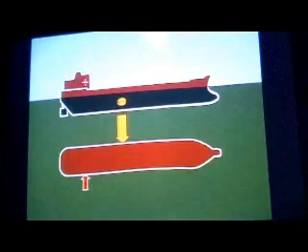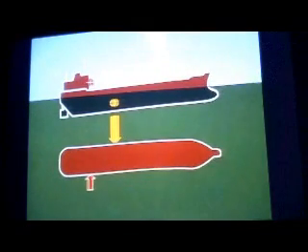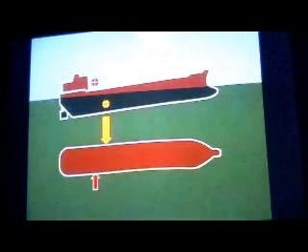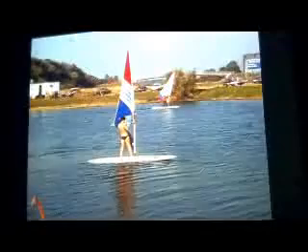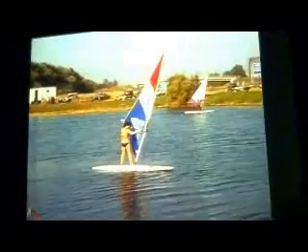Trimming a vessel will cause a similar but less marked effect. Heading and drift direction will change as the turning moments alter. This has little effect on the longitudinal and lateral forces and therefore does not significantly alter the drift speed. The same principle, trimming, is used by windsurfers to steer their boards. The movement fore and aft of the sail's center of pressure is used to alter the board's heading.